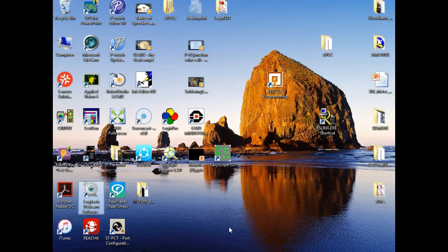So y'all document these on your ladder diagram before you start connecting them up. And plus it helps me. So when I come back there, I'm not going to try to figure out two different documents, right? I'm not going to try to figure out the manufacturer numbers, which are written on these terminals for you. By the way, they also put a schematic of what's going on up here in the upper right-hand corner. So you can actually see the actual schematic diagram of the device itself.